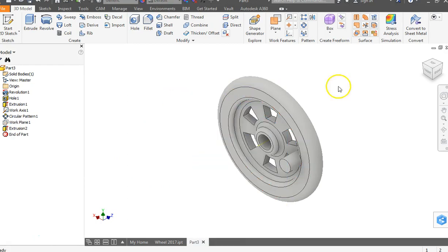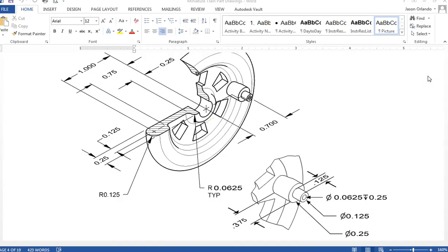Visibility, uncheck. Okay, so the last little piece to this is this extra little cylinder needs to pop out, and then there's a hole in it. And if you study this detail view, you'll see that the hole, this little line shows the hole, is deeper than this piece comes out. So we're not going to do them at the same time since they're different depths. We're going to bring this out the 1/8, and let's see, the radius is also a 1/8, so remember that, an 1/8 and an 1/8.